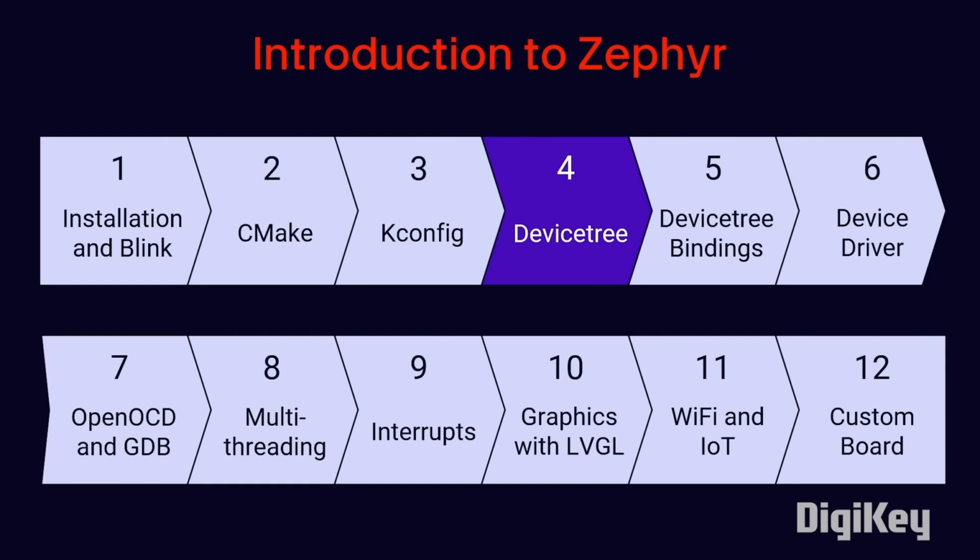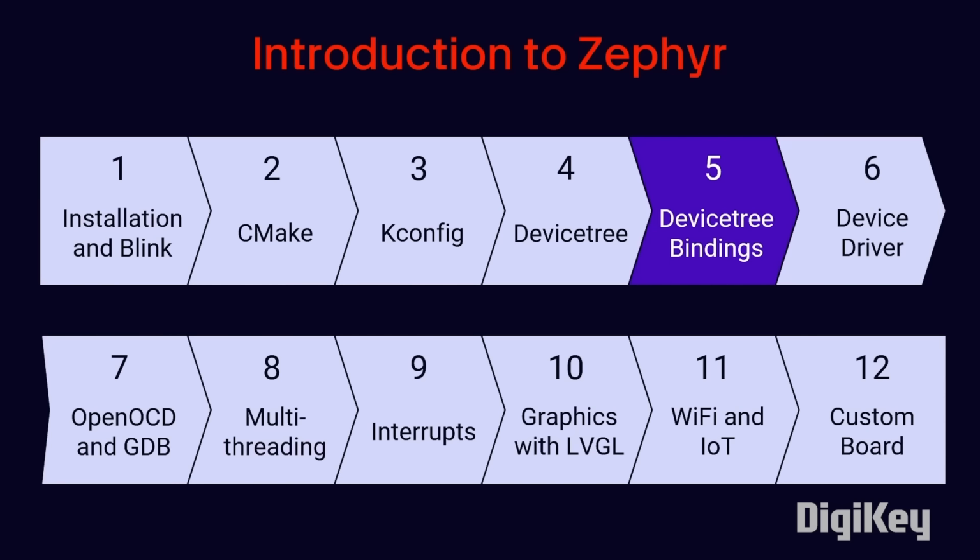We'll go over the device tree syntax first so you can start to get some practice reading device tree source files. You'll also see how the Zephyr build system compiles all of the device tree fragments scattered throughout the source code to produce a final device tree for your project. Then we'll talk about bindings. This is where Zephyr differs from Linux in how device drivers are handled.